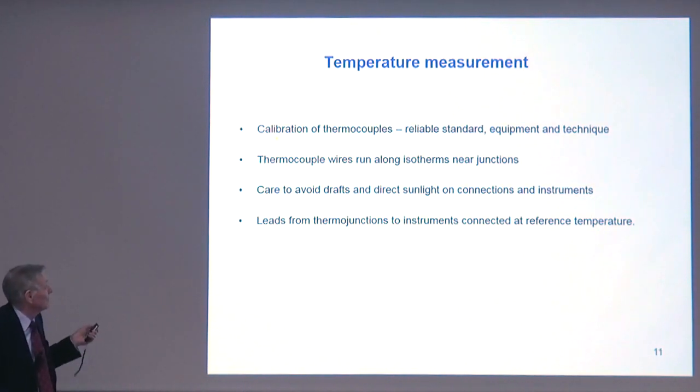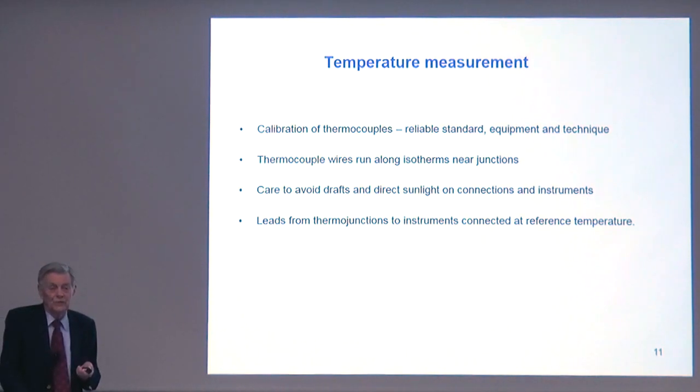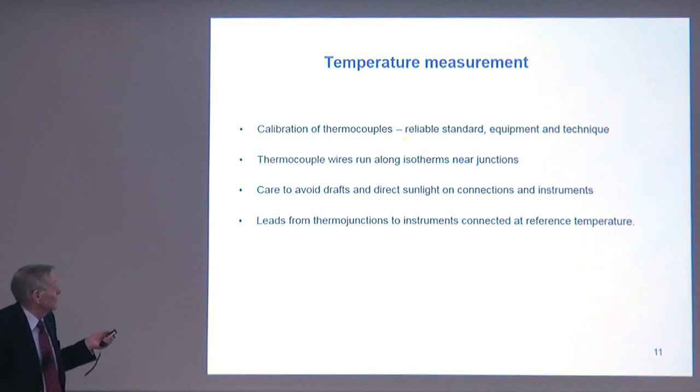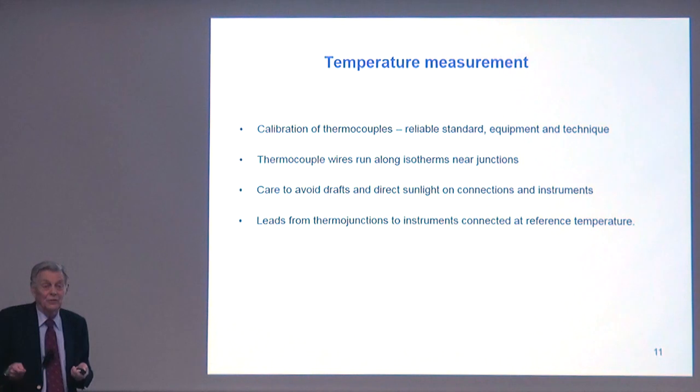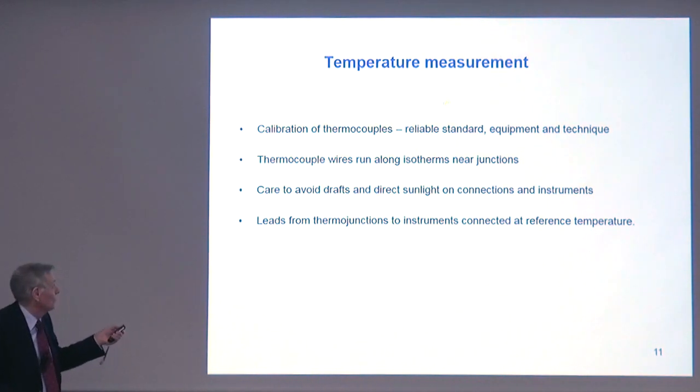Temperature measurement. When I started my research, the first thing my advisor, Professor Lefebvre, said was, go to our National Physical Laboratory for a week or maybe 2 weeks and learn how to measure temperature accurately, properly. So you need a reliable standard, you need good equipment, and you need good technique. You can't just buy thermocouples and stick them in and that will give you the answer. There's much more to it than that.